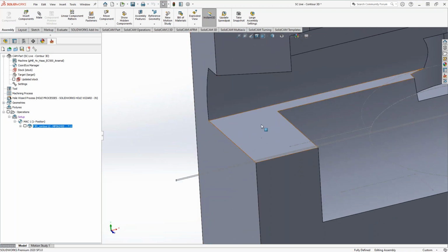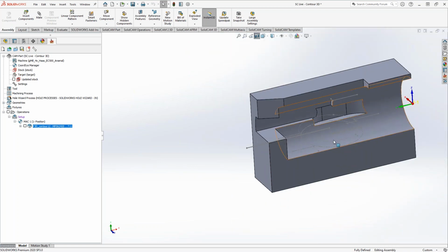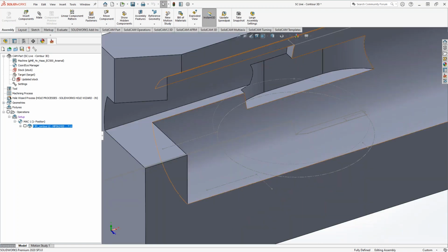So that's what those two lines are, and they're made on a plane that's 10 thou and 15 thou parallel to that one. Then on the bottom, again, controlling the bottom of the tool and the center of the tool, I created these chains here, this one and this one, that were offset from those edges there. This is pretty much on size with the radius of the tool. So this line and this line right here are basically the tool just goes in, comes out, and that's it.